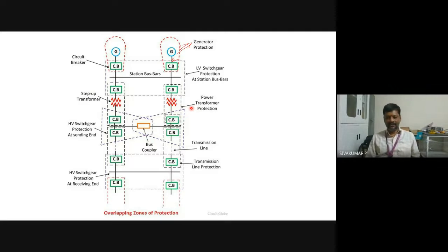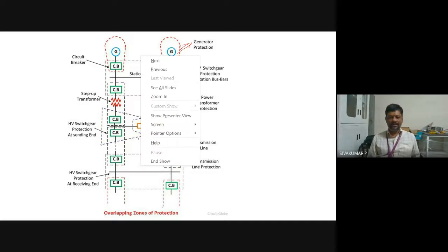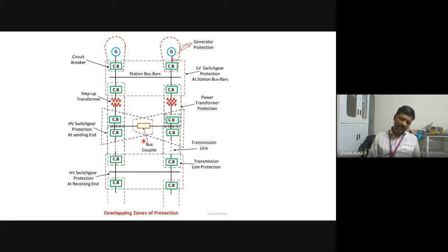Okay. So if you are not setting the proper tripping time, the overcurrent will also be announced. That is the problem here. Again, this overcurrent relay can be identified where the problem occurs. Unnecessarily, this bus coupler is tripped. So to avoid this problem, we have introduced numerical relays, nowadays computerized relay systems and SCADA. So many technologies. The current technology is PMU, right, which can be introduced. So this is the way.